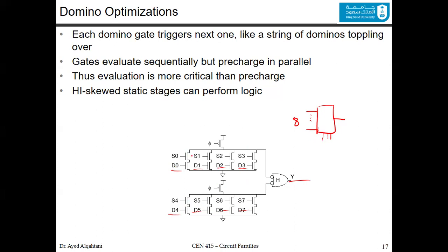But this is a special multiplexer where you have exactly the same amount of selection lines as inputs. So you have also 8 selection lines. And it works as a one hot encoding multiplexer, where if you want to choose D0, you make this on and the rest off. So this is for the selections. Also, this is a special kind of multiplexing. Now, where does the domino play its part here?